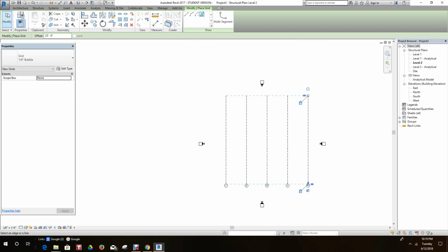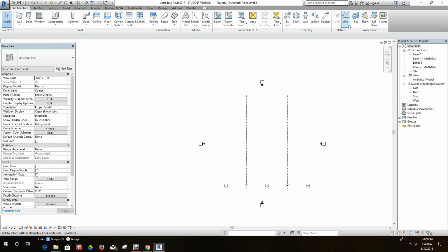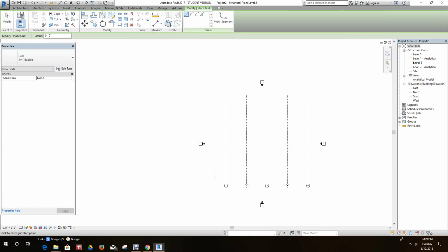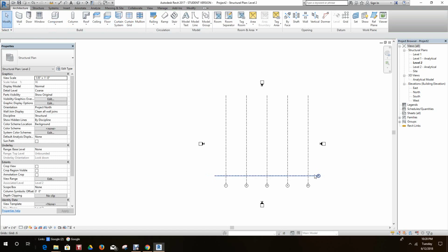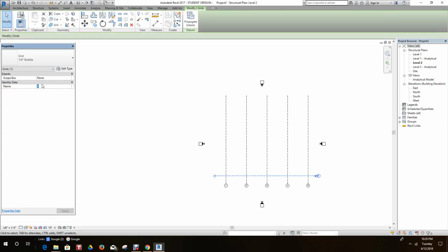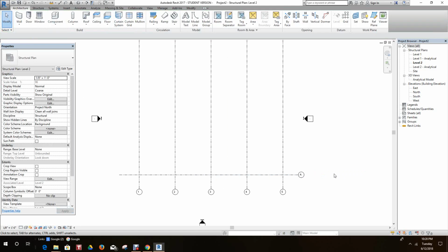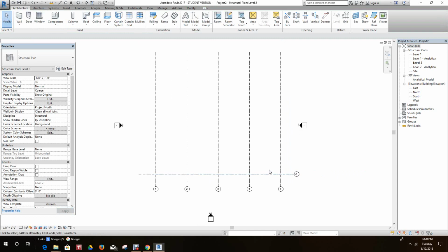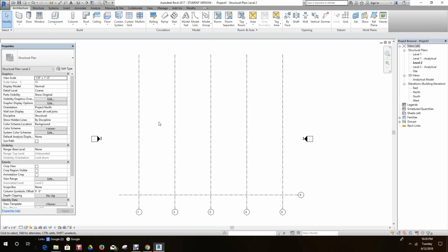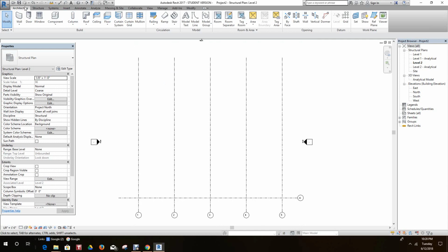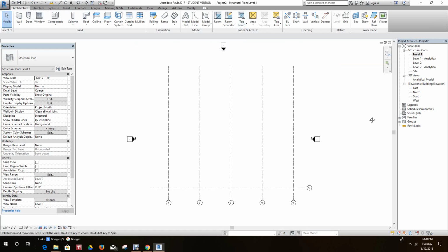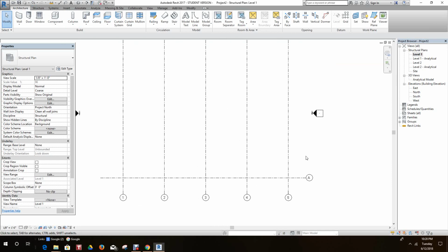Okay. We have a modify key. Go back to grid. We'll select the grid line in this direction. Go back to our modify key. Select that grid line, and we want to name that A. Okay, and make this really simple. Let's go 25 again. Oops, sorry. We want to go down to level 1. Okay, we want to be in level 1 here.